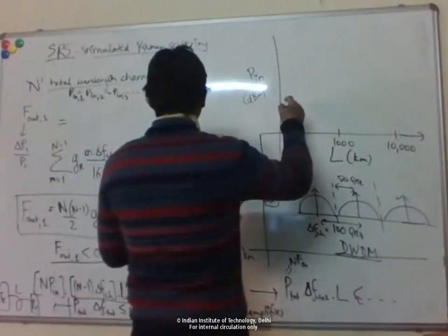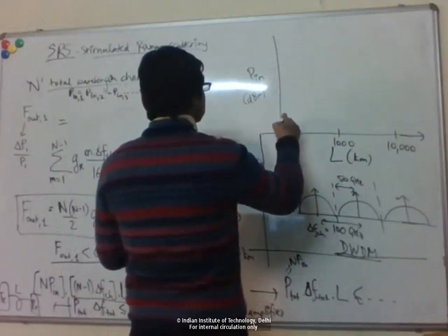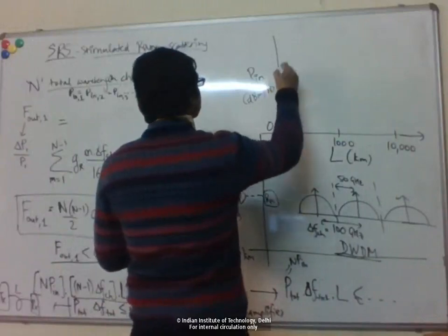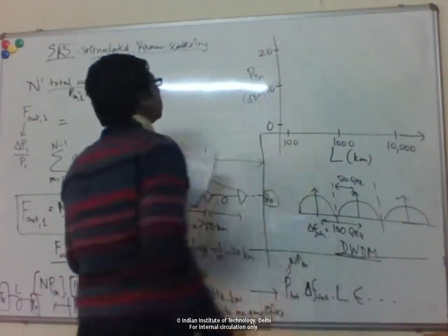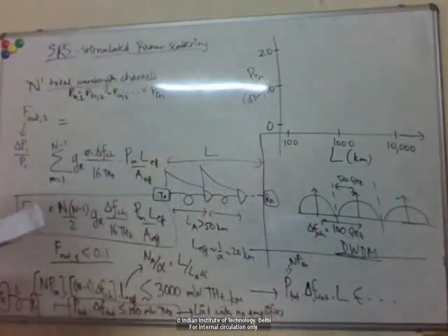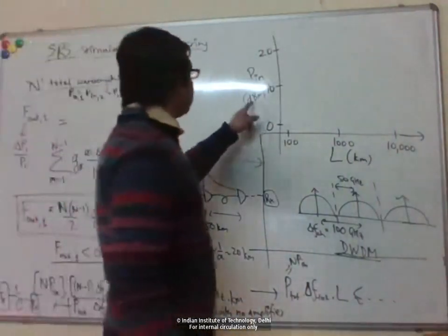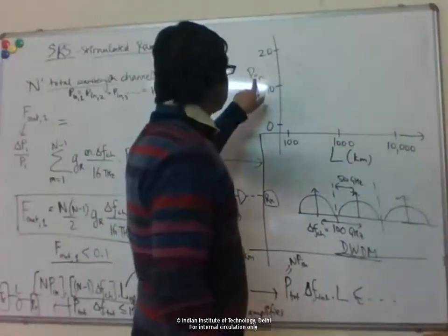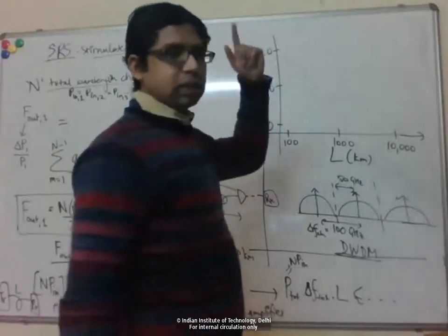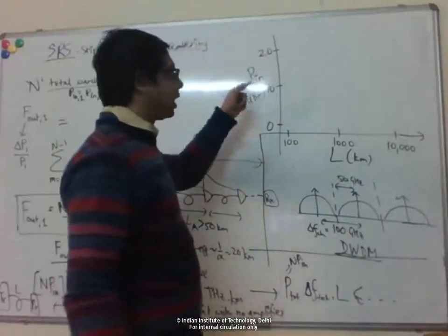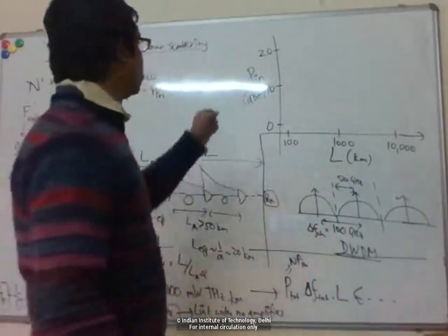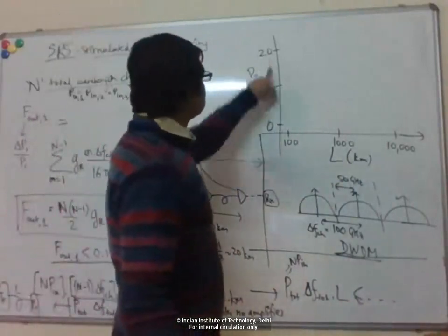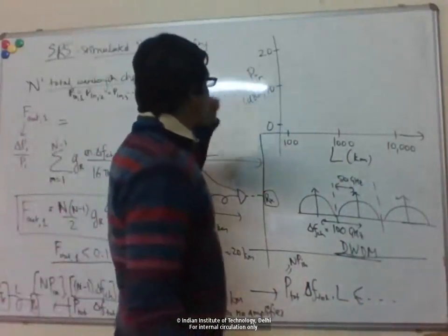And here we've got dBm. You know how dBm is defined. A linear scale in dBm is actually a log scale in watts, because this is computed by taking the log of the power in watts. So this is also a log scale in absolute power units.